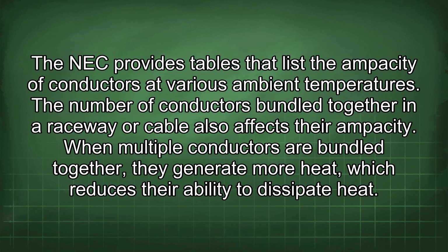The NEC provides tables that list the ampacity of conductors at various ambient temperatures. The number of conductors bundled together in a raceway or cable also affects their ampacity. When multiple conductors are bundled together, they generate more heat, which reduces their ability to dissipate heat.